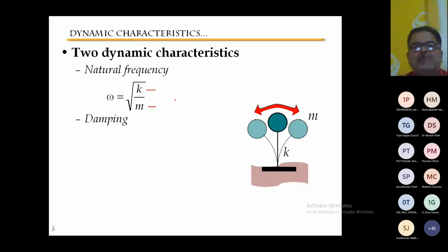If I'm saying high-rise building will be affected, I'm wrong, right? What is the reason? The reason is a building is having its own frequency, right? Now, when I'm talking about a low-rise building, then in case of a low-rise building, the stiffness is very high. If the stiffness is very high, then the natural frequency will be high, right?